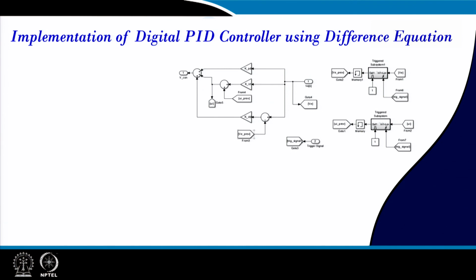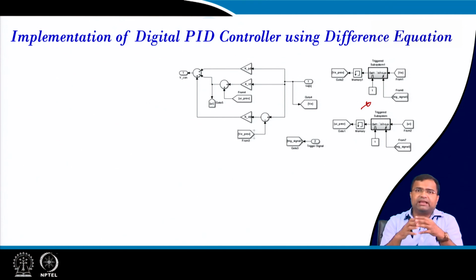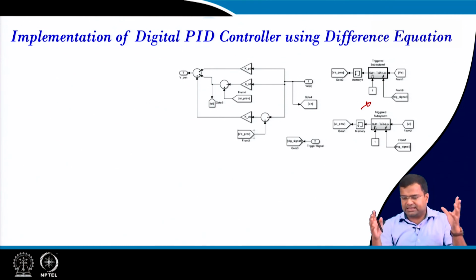Okay. So, we have learned that we can sample in the controller either by event clock or by adjustment. We can adjust the edge of sampling with respect to the switching clock by using a difference equation, and by using this clock driven difference equation we can implement any type of controller, PID, PI, anything.